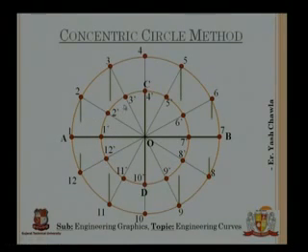These are on the left hand side of the circle, so we draw lines from right to left. For those on the right hand side of the circle, we draw left to right. Each line will intersect these vertical lines, and we will mark these points very neatly.